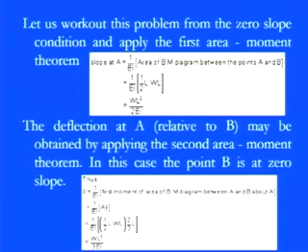So you see here, in comparison to the previous method, it's a very simple method, no boundary condition. Straight away, once you have a feeling of the bending moment diagram, you can simply have the slope as well as the deflection. So this was a pretty simple part.